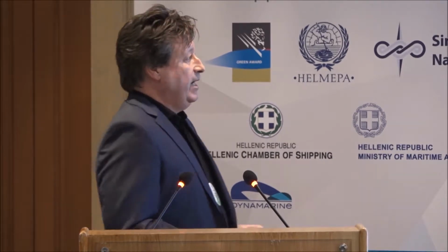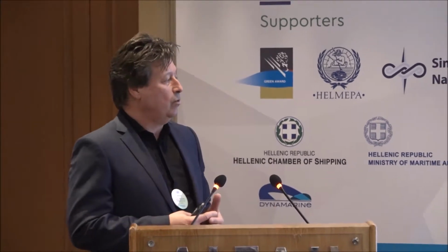In order to run an analysis, you need three basic sets of data. You need data for the berth, so the type of berth, the tidal data, the water levels, or regular tide data, or tidal charts. You need the layout geometry, so basically you're specifying an X, Y, Z position for everything, for the hooks, bollards, and dredge depth and heights and so on.